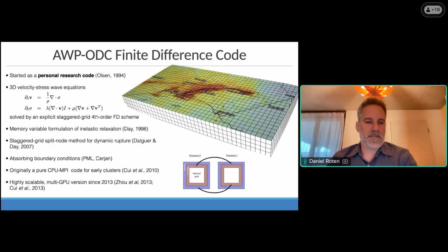Only recently we've been able to go to the resolution that is required to capture those wavelengths for really large earthquakes. Another challenge with going to those higher frequencies comes from the physical effects that dominate at frequencies above 1 hertz, in particular topography, scattering, and plasticity, which can happen near the fault or near the surface, which was the focus of my research in the past.